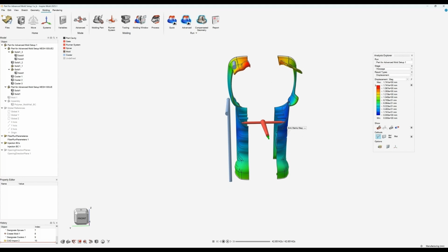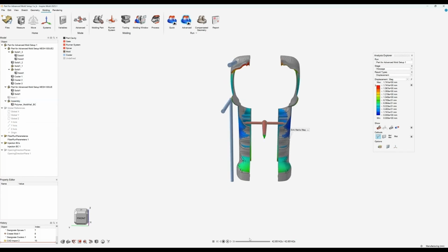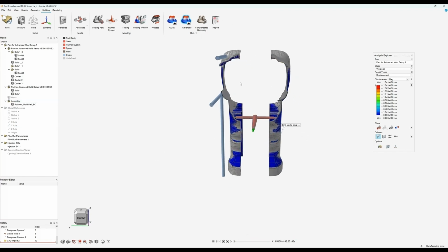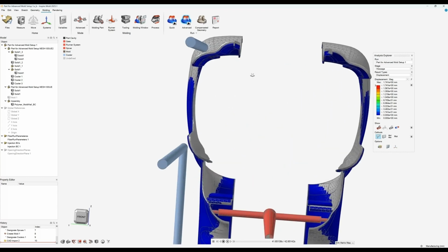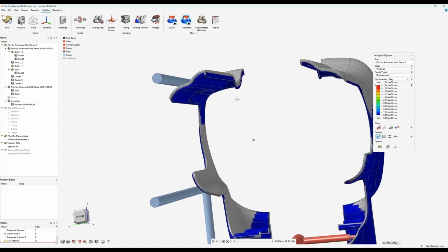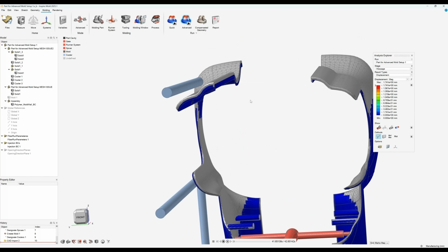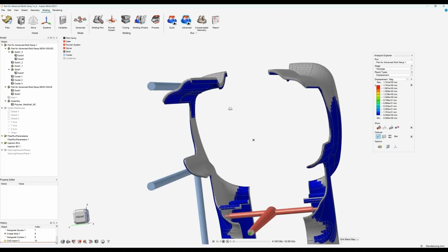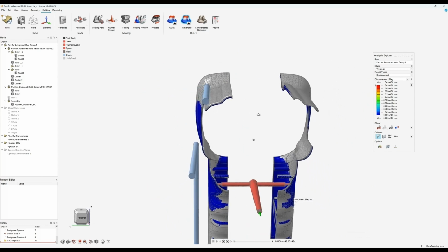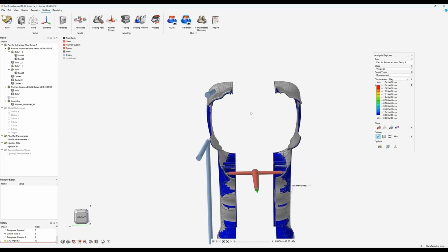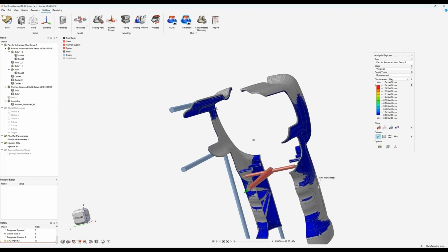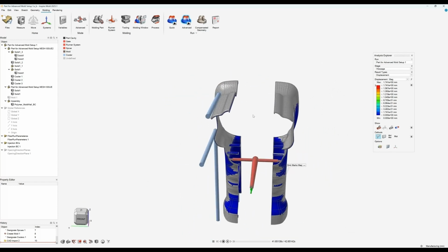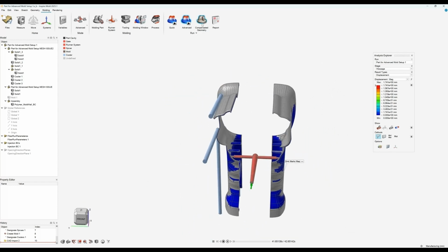So you can literally click this button here, it exports an STL file. This would give you something that looks like this. So if I bring this back to what the part looks like, you can sort of see it overlaid. The silver part is the compensated part, the blue part underneath is the original sort of geometry, and we can see that it would hopefully warp into the shape that we wish. So we can see that there. So that's what that compensated geometry does.